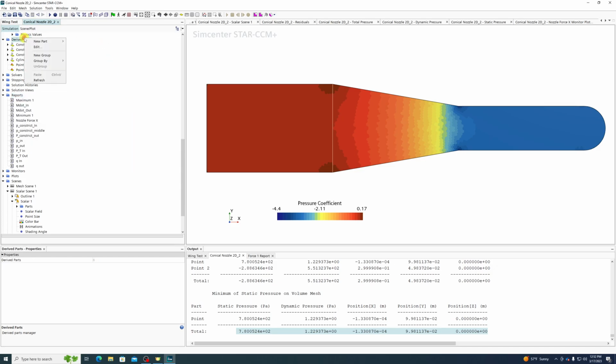And if you don't have a surface where you need to, you can use various derived parts, specifically probes and sections, to measure values where you want. You create a new surface that is derived from the existing geometry in some way. And this will allow you to measure the values where you want. Clearly, these are not the only derived parts. You also have cell surfaces, iso lines, constrained streamlines, vortex cores, etc. Those are also useful in different contexts.